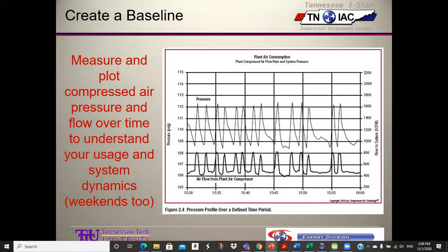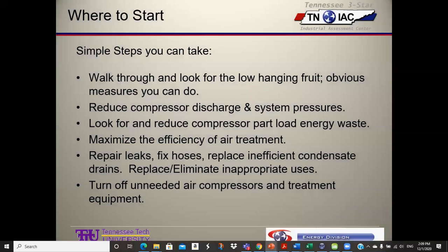Measure and plot compressed air pressure and flow over time to understand your usage and system dynamics, weekends too. So, taking those measurements, amps, pressure, flows, and plotting them up will really give you a lot of information on how a system is operating. Where to start? Simple steps you can take. Walk through and look for low-hanging fruit, obvious measures you can do.